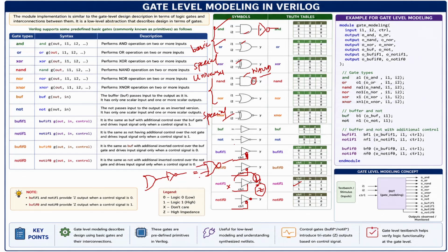Then how will the enable pin symbol be, sir? Here, gates don't have any enable signals because combinational circuits mean continuous assignments. Immediately we give the input, immediately I get the output. Generally, I'm asking about the enable pin symbol. Enable signals are in combinational circuits like encoder, decoder, multiplexer, demultiplexer.